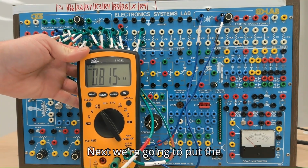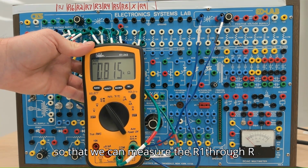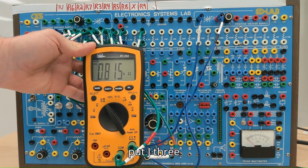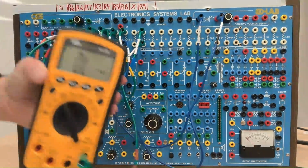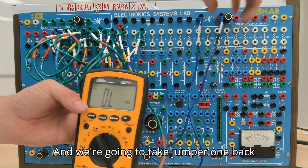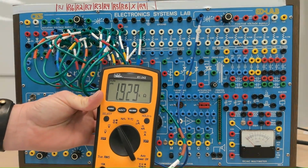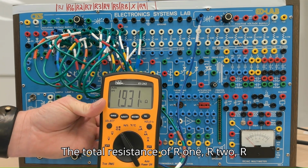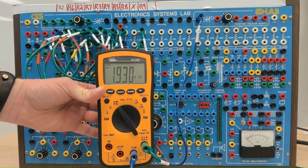Next, we're going to put the leads back and put new leads on so that we can measure R1 through R5, get a total resistance between those 5 resistors. So we're going to put J3 back to the bottom of R2, and we're going to take jumper 1 back off the voltage source. The total resistance of R1, R2, R3, R4, R5, 1.931 kiloohms.